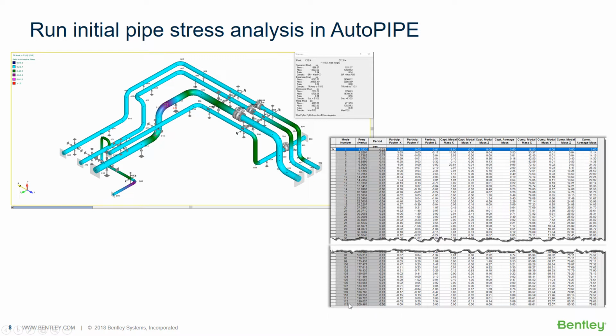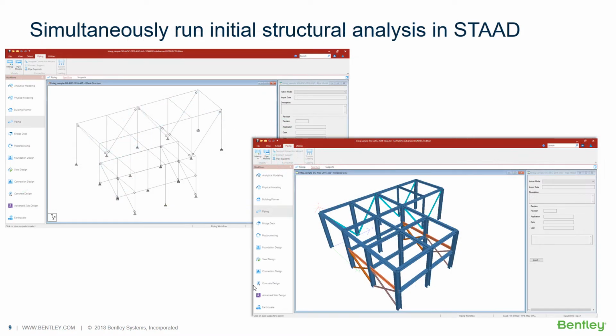The 112 modes is what we're actually using to extract the mass participation. And our cumulative average mass that we're seeing is 79.66% of modal mass. We're able to extract 79.66% of our modal mass, and this would be used for our dynamic analysis results if we added in a dynamic load. We will see how this changes.